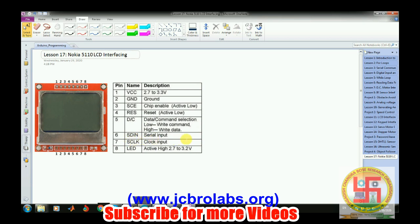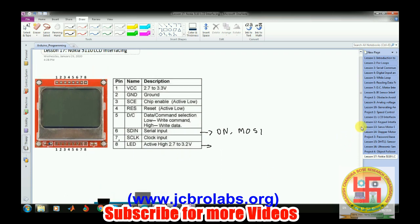So generally there are several names for this SDIN. This can also sometimes be written as DN, or in some it can be written as MOSI, master out slave in. And then pin number 7 is clock, which has to be applied, and the last pin is to control the backlight. Okay, so these are the pin numbers, and we will be connecting this to the Arduino.